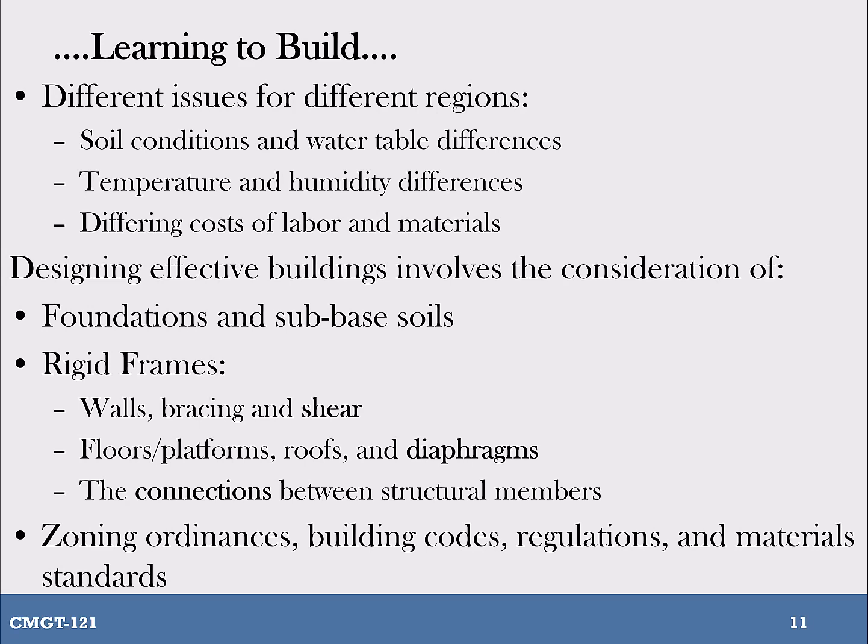In some of the hurricanes, like in Florida, I remember Hurricane Andrew was the first time they really understood this and started changing the building codes. They had garage doors that just weren't strong enough. Here in the south with the high winds, if your garage door is not strong enough, it blows in, and then the garage ends up acting like a big windsock and inflates and tears the building apart, literally.